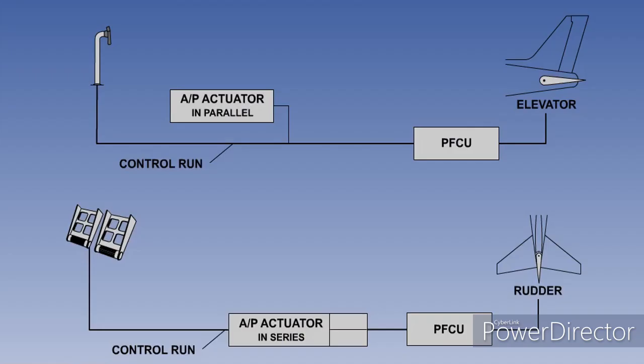We will start by looking at the autopilot's muscle, or how it moves the aeroplane's control surfaces. The autopilot achieves this by using either rotary or linear servo motors, of which there are two basic types. Servo motor actuators are either electrical or hydraulic, and can be connected in one of two ways with respect to the remainder of the flight controls.